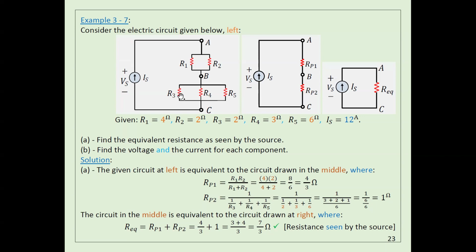So this is it. Again, there are different ways, but this is a very easy and straightforward way. Now the question is, how can you get the voltage here? How can you get it? This equivalent resistance, I times the equivalent resistance, will give you the same voltage here. I already got RB1, and RB1 here is 4 divided by 3 ohms.